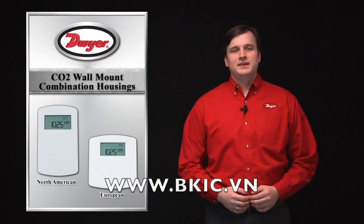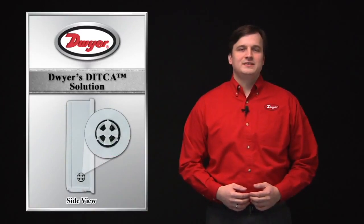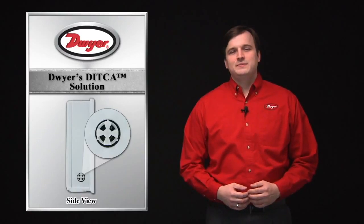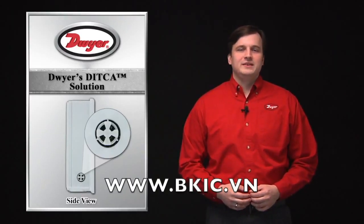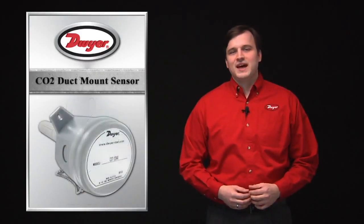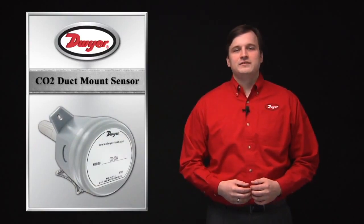The North American and European wall mount combination sensor housings feature a separate temperature sensor that is thermally isolated from the internal space of the enclosure. This has been tested to prove a more accurate measurement of the airspace temperature, which is then used to more accurately represent the RH level in the room. This is not used in the duct mount sensors, as the airflow across the sensing element draws away the heat created by the circuitry.